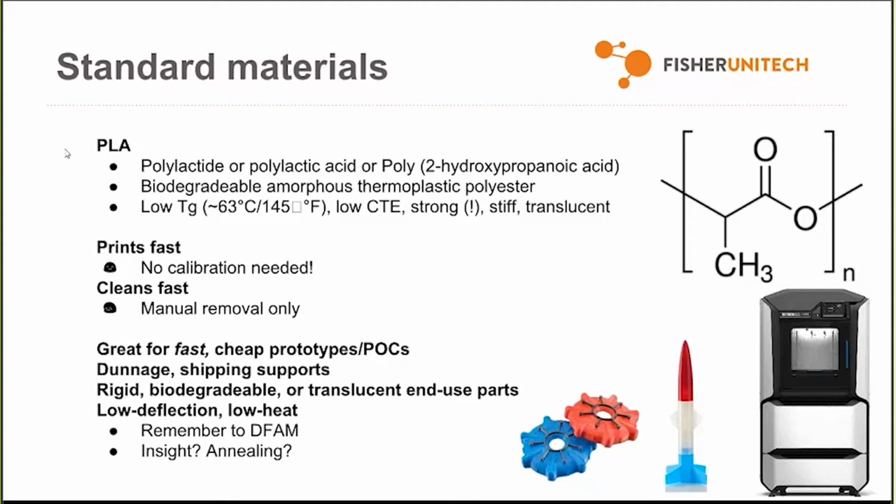It has a low coefficient of thermal expansion, and that pertains to how much a material expands and contracts as it's heated and cooled. So because of that low CTE, it moves less when it's heated. And again, since it prints cooler, there is less heat to move it in the first place. So I think that allowed PLA printers to have an open frame, which in turn allows them to be built much cheaper, and I should note, without violating Stratasys patents.